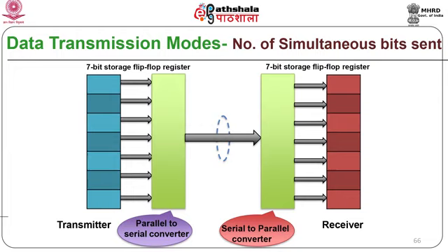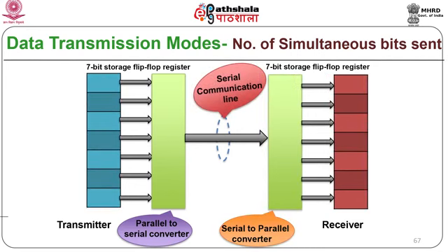When a clock pulse is applied to the sequentially cascaded flip-flops of the shift register, the bits of the word are shifted from one flip-flop to the next. At the end of n clock pulses, all the n data bits of the word will be transmitted. The transmitted serial word over the communication link is then received by the serial in parallel out shift register at the receiving end. Further, the parallel data outputs from the shift register are transferred to the computer circuits.